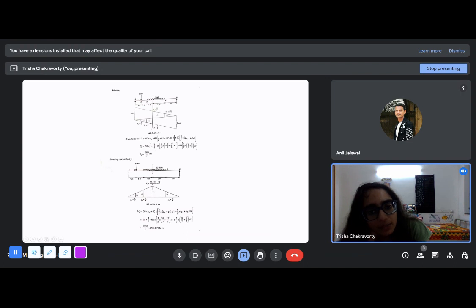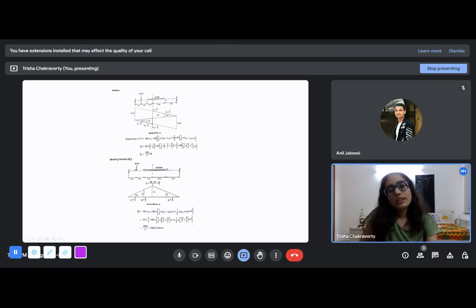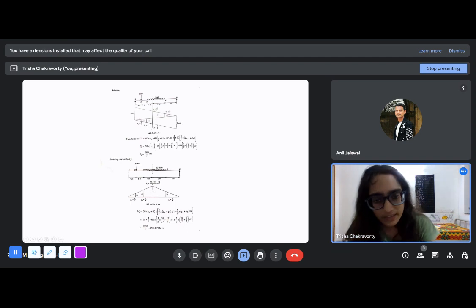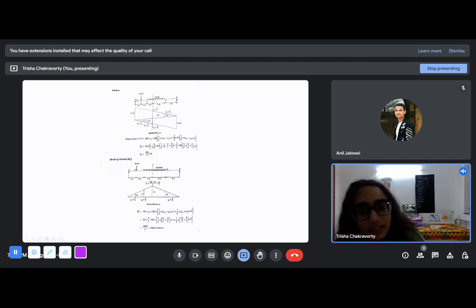Then you draw the ILD below the actual loading. You don't know the actual loading initially. First, just draw the ILD and forget about the actual loading. Now you come to the position of the loads. Like this 50 kilonewton is applied at 1 meter from here. Suppose this point is called C. Now we need the ordinate of the influence line diagram at C. We can find it using similarity of triangles. This is 3 by 7 at 3 meters, so at 1 meter it will be 1 by 7.